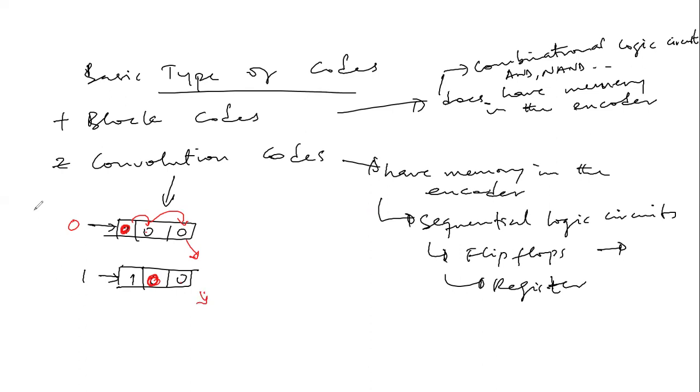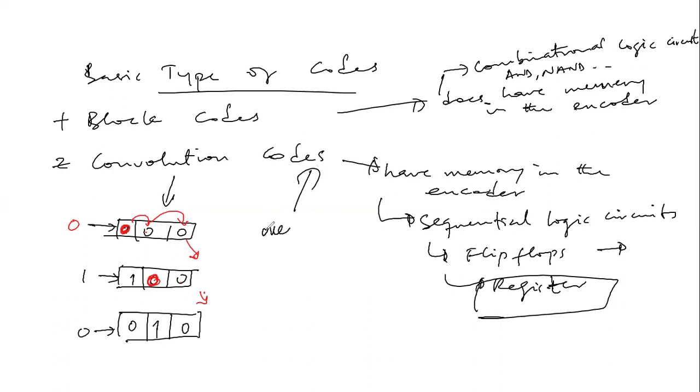And now, if we have this as our initial state, which is 1, 0, 1, and we feed in a 0, that 0 comes in here, this 1 moves to the next shift register, and this 0 moves to the next. So you now see that here we are able to hold on to the previous bits while we take in new bits. So hence, the memory has memory. Okay. So we are going to see them also.